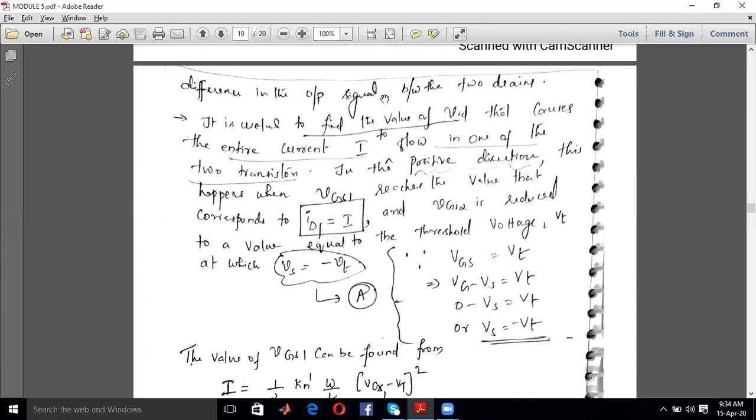So these are the two basic points of the working of this differential amplifier. Now we are going to check the differential mode range, as we have already checked the common mode range in the previous case. What do you mean by common mode range actually? The common mode range was the range of input voltage, between an upper limit and a lower limit, which you should give so that your amplifier is rejecting your input. That was the common mode range actually.